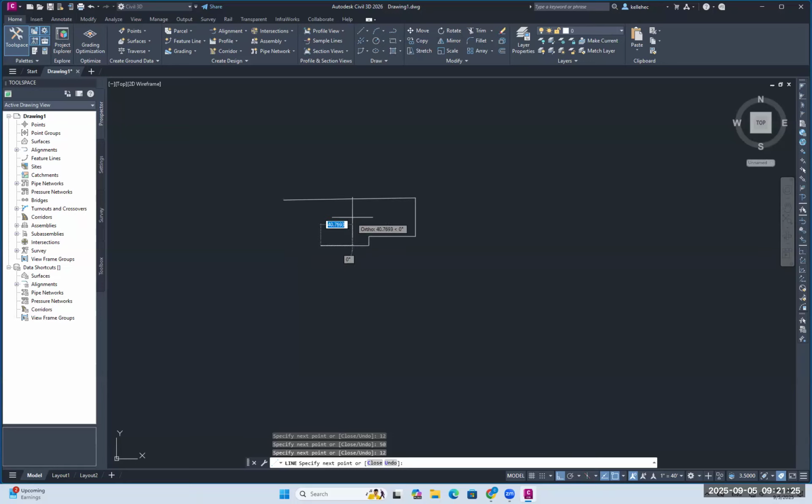And I've got, oops, that didn't go in. I might have made a mistake. Oh no, I made a mistake. So what am I going to do? I'm going to erase. Just did that little area. So I'm going to click on line again. I'm going to click here. And I have my ortho on, so I'm going to go 12. And I'm going to make sure I'm pointing this way. I'm going to say 60. And then I can finish right up to the very tippy top. And it's not exactly 50, that's okay. Again, escape is going to get you out of any of those tools.